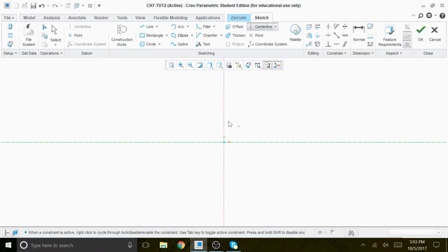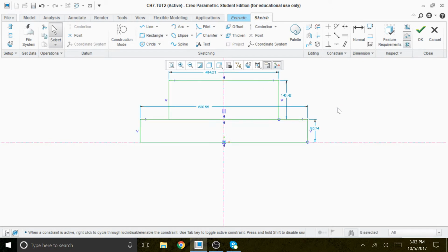Okay, so I'm going to create a rectangle here. It makes it symmetric. Make sure that it's symmetrical, and then we can do another feature in here. We're going to just stretch it until we see the two green arrows. It shows as symmetric. So we're going to give a dimension here, 8.